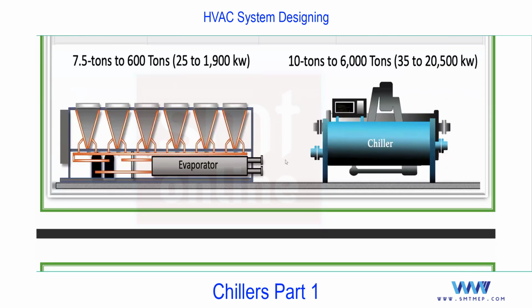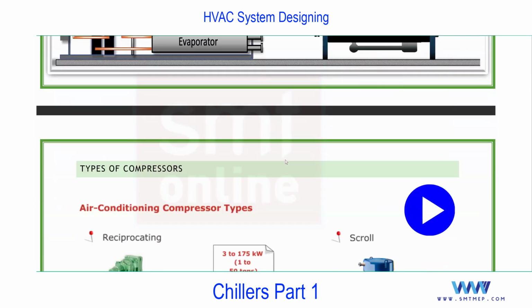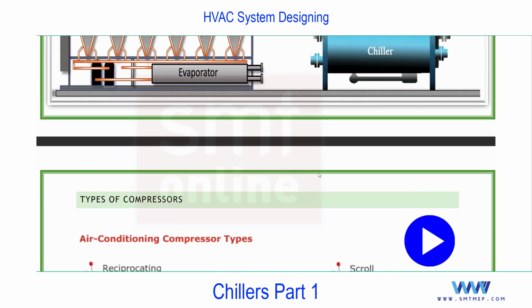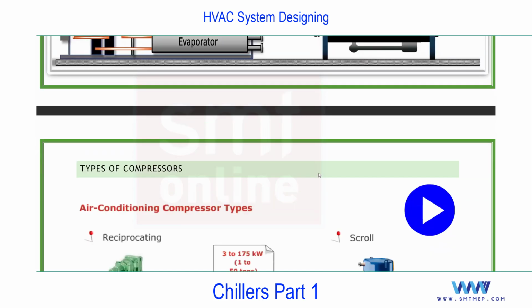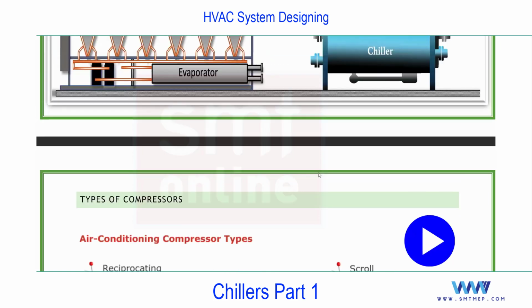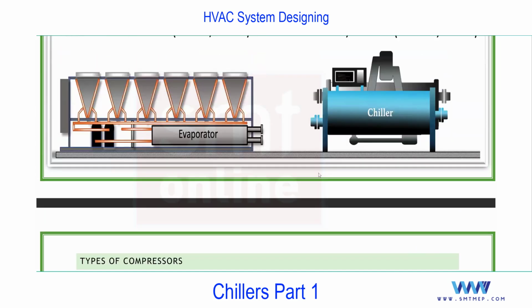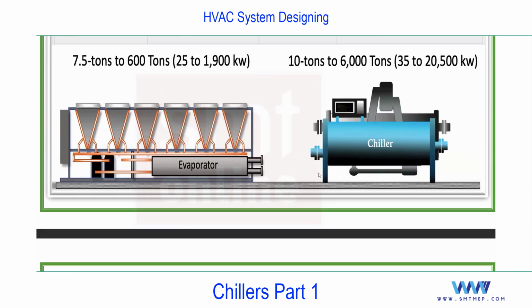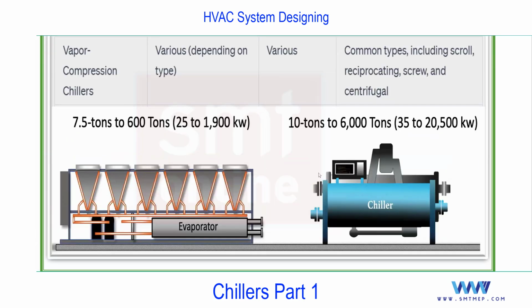Okay. One question. In actual practice, is anyone going to install a 7.5 TR air cooled chiller or water cooled chiller? No, not commonly. Chiller is generally for big projects. Okay. It's available for a small project as per the special application. But suppose one client is asking for a chiller even for a villa, so we can use this. But the initial cost is going to be high, so you'll not find the small capacity chiller. It can be for a process control sometimes.